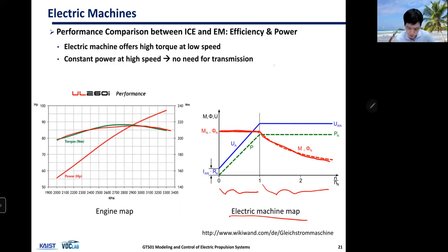And in fact, this is one of the nice characteristics electric machines have. And what this means is you can generate high torque at low speed, and you reach this maximum power quite fast. Whereas for internal combustion engines, if you want maximum power, you have to operate at high speed, right? And for most of the region, your power is lacking. So even if the engine can produce a maximum of 100 kilowatts, at low speed you just cannot produce that full potential. But electric machines can actually provide all of that power from low-mid speed. Okay, approaches that max power fast,